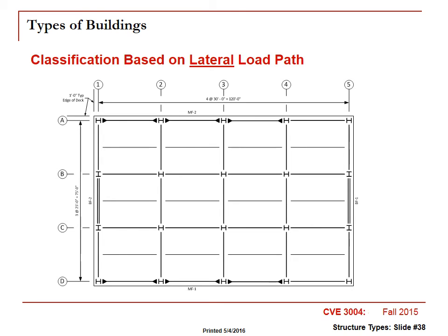This is really just showing you a floor framing plan. You probably know this, but maybe you don't. If you look at the top and bottom, you'll notice the exterior beams between certain columns have little darkened-in triangles on them. Those stand for moment frames.